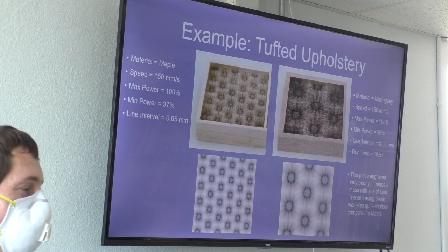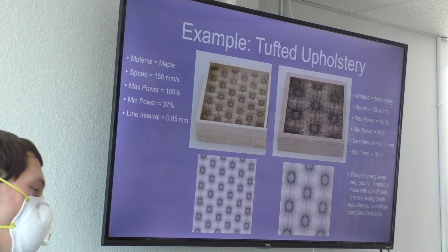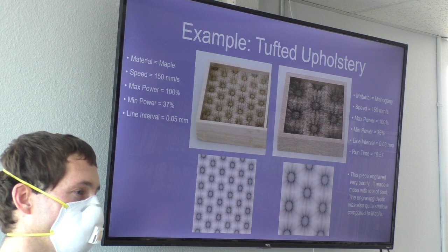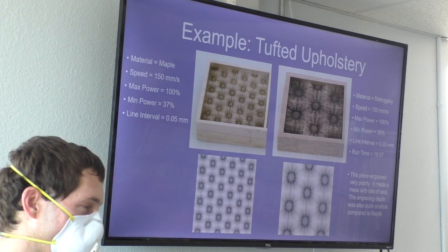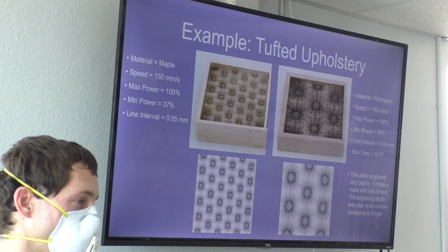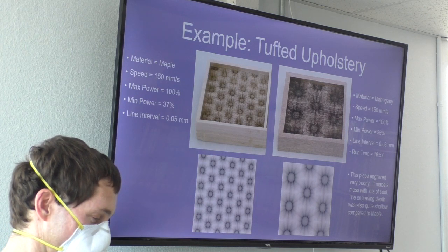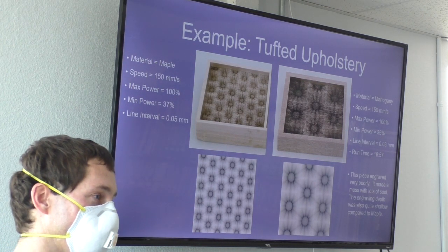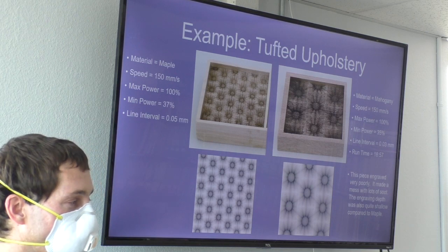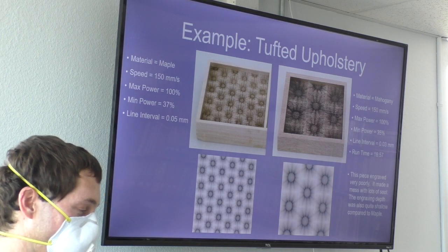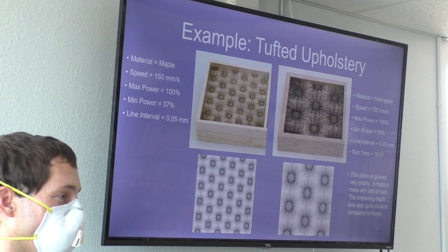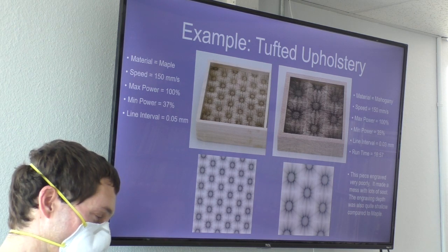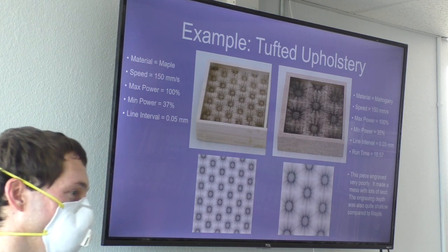Yeah, so for illustration of the difference in just experience in the machine, when you're doing the maple, there's almost no smoke. It's basically just turning everything to CO2 and water vapor. The end result's just kind of got some goo and blackness on it, but besides that, it's good. The mahogany one, it was just shooting out soot everywhere. It coated the piece and the laser head. I tried to wipe it off, but it's all sticky too, so it was a big mess.